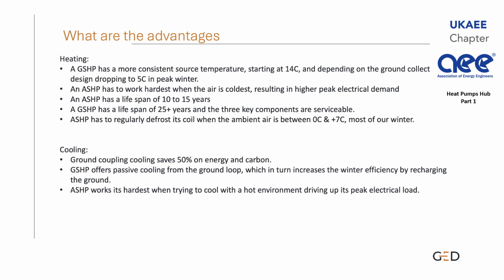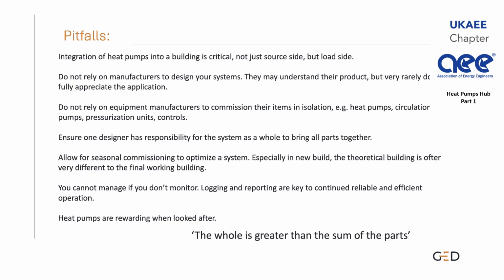The pitfalls: integration of heat pumps into a building is critical, not just the source side, but also load side. Do not rely on manufacturers to design your system. They may understand their products, but they very rarely appreciate the whole process and the whole system. Do not rely on equipment manufacturers to commission their items in isolation. So heat pumps, circulation pumps, pressurization units, etc., because they're generally not joined together. Ensure one designer has responsibility for the overall system design that brings all the parts together.